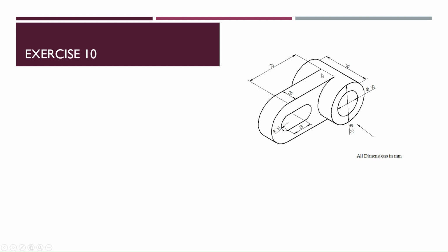And also you can see that on the outer periphery of the cylinder, there comes a rectangular protrusion to a distance of 70 mm from its center. And then towards the extreme left of this rectangle, I've got a semicircle which has a diameter of 50 mm because the total height is equal to 50 mm. Correct? So these are the observations that we can make. Also, there is a through elliptical hole of radii 10, and the center distance between these two is equal to 25, and the thickness of this is equal to 20. So with these observations, let us try to create the 3D part.